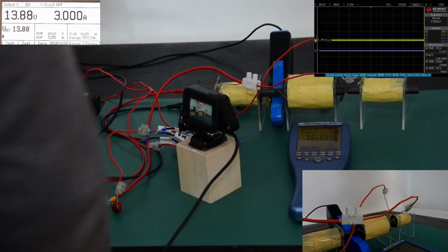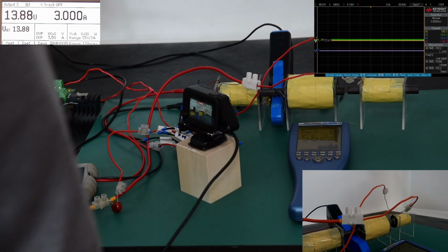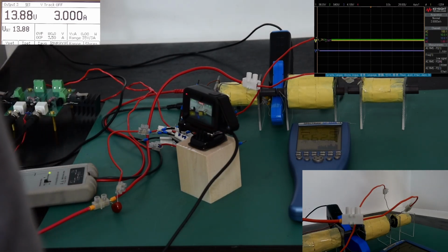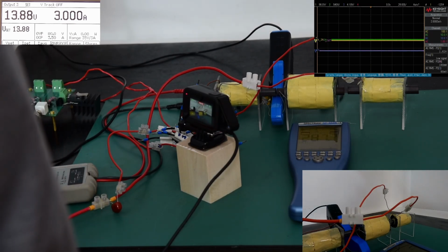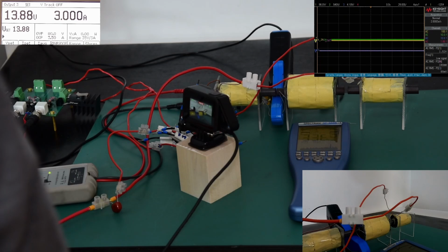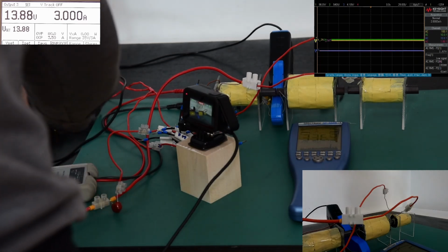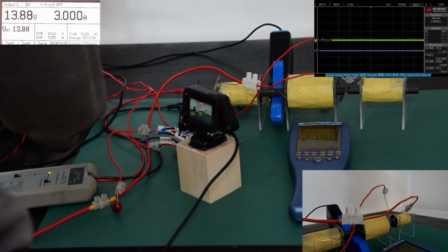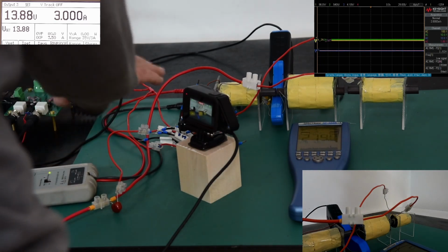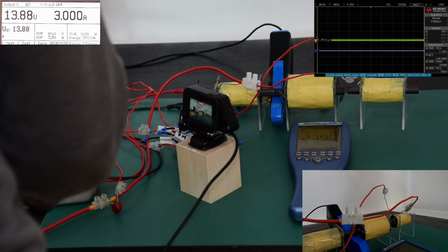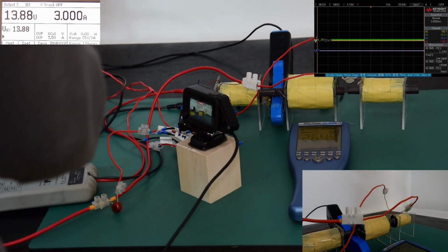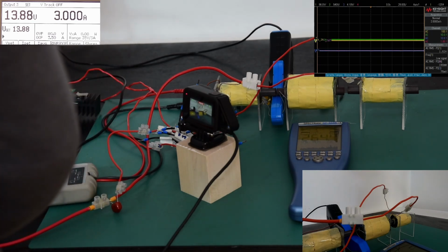If I energize that now, I have it already at 13.88 volt, and remember we had an output of 1 watt because it's a 50 ohm sine wave into 10 volt peak to peak. Here we have now 13.88 volt. It is not 100% perfect with the energy distribution. It should only be 10 volt, but because of our mismatch of the impedance, we have to get higher in the voltage in order to achieve that.